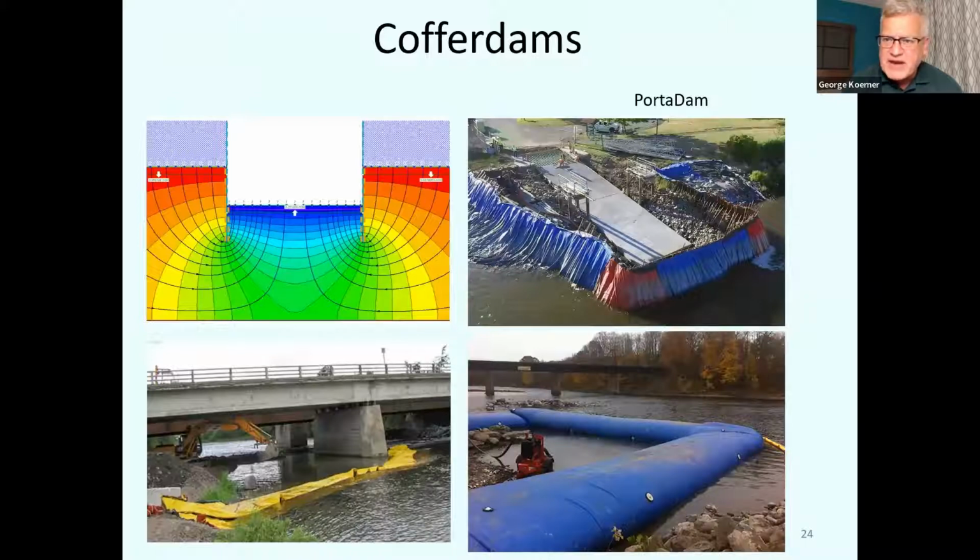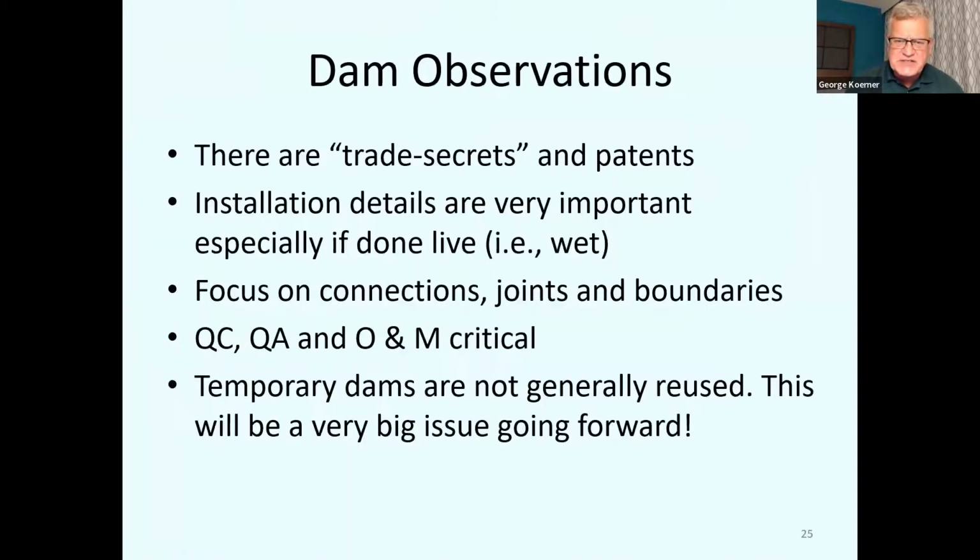The geomembrane is temporary, typically only in the neighborhood of 1 to 3 years. It has to have tremendous tensile reinforcement associated, so it's typically scrim reinforced material and used in conjunction with sheet piling or some sort of scaffolding system.